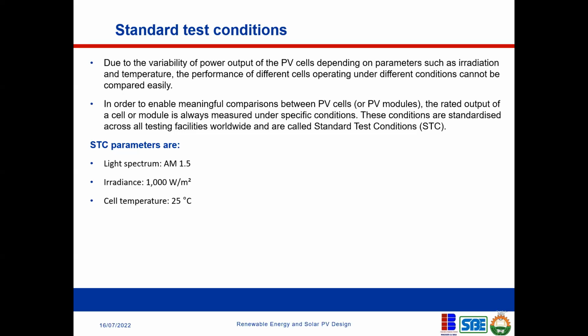It could be surprising that you could have a solar panel that is rated 400 and you could get over 400 watts of power out of it. It is possible, depending on these conditions. Remember when I said that if the temperature increases, it reduces the power output. Now think about it the other way. What if the temperature reduces? So instead of 25, the temperature goes below 25 degrees centigrade.